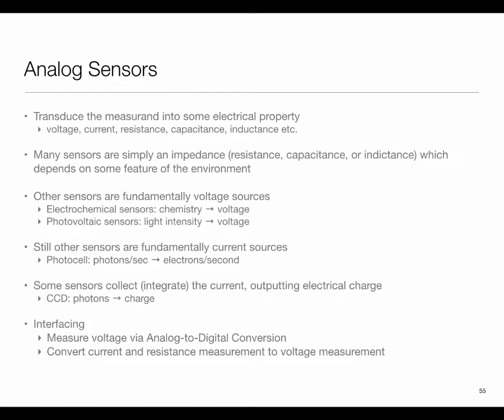So many sensors, fundamentally, deep down, all transducers are analog. They take a physical signal and they report it as a resistance, capacitance, inductance, or some other electrical property, which you then translate into ones and zeros after digitization. There are sensors which are fundamentally voltage sources, and there are sensors which are fundamentally current sources. But that pretty much covers things.